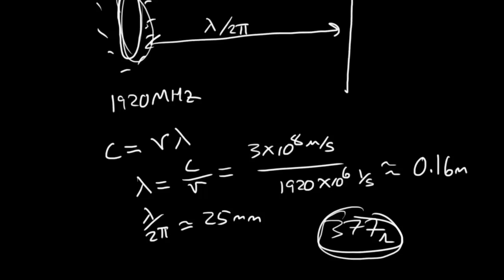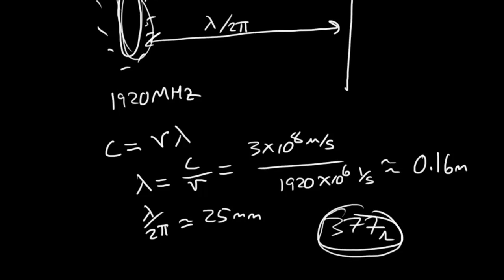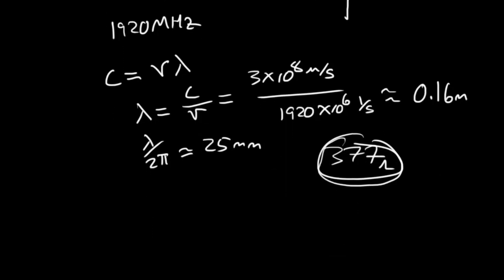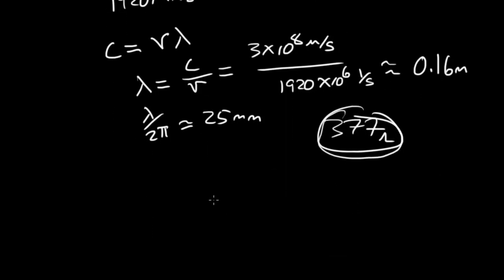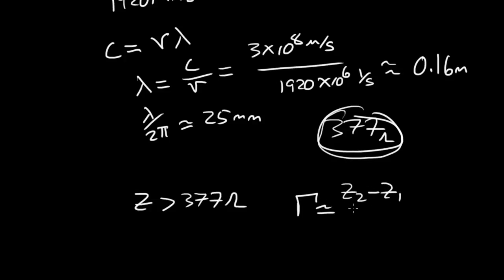Actually, I want to note that since I think we're dealing with the case of a cell phone radiation, primarily electric field radiation, the Z of the medium between the cell phone and your scalp, or the air, would be greater than 377 ohms. And the reflection coefficient then would be Z2 over Z1 over Z1 plus Z2.